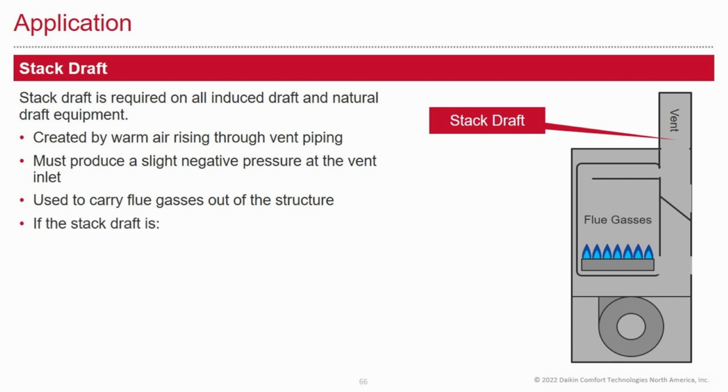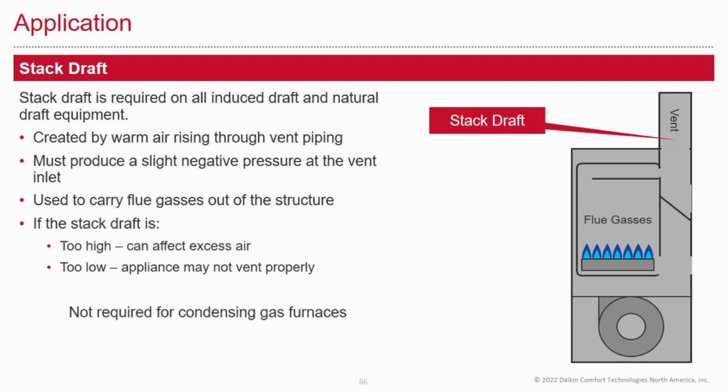If the stack draft is too high, it can affect excess air on your burners. If it's too low, the appliance may not vent properly. It is not required for condensing gas furnaces.